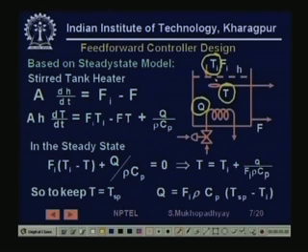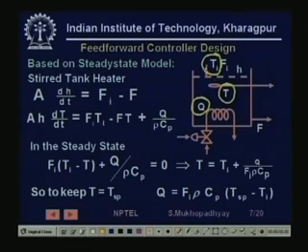Now, if we did a feedback control, then if there is a temperature change, that would have to affect T first, and T will change only when the whole mass of the liquid changes. So, a lot of time will pass before T can change, because this has to mix through the volume. Rather than that, we are assuming that we sense this Ti, suppose we put a temperature sensor, a temperature transmitter, and put a controller and feed it forward.